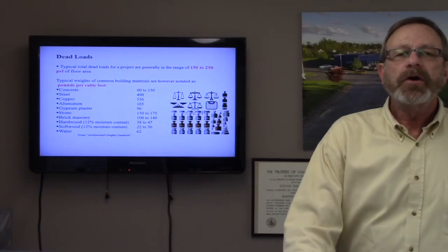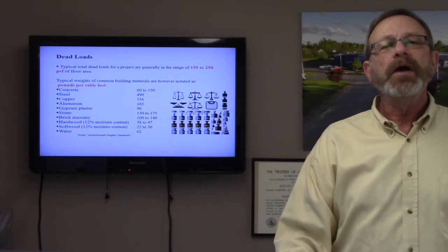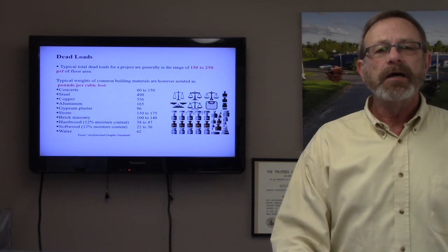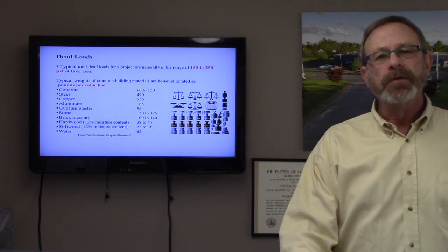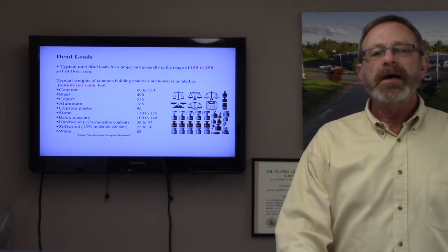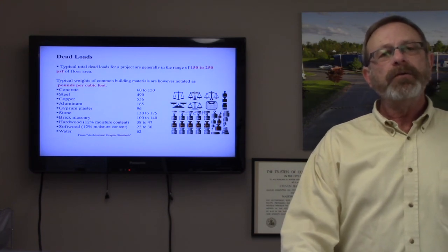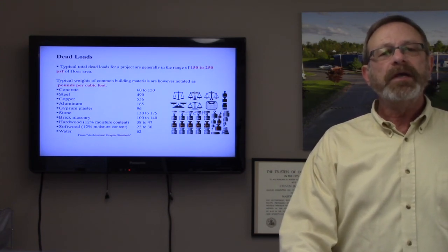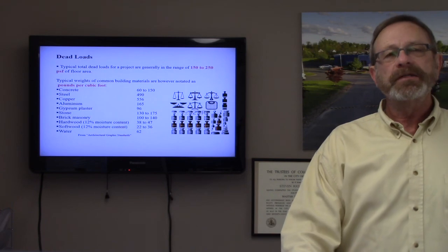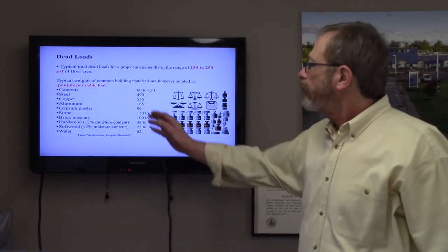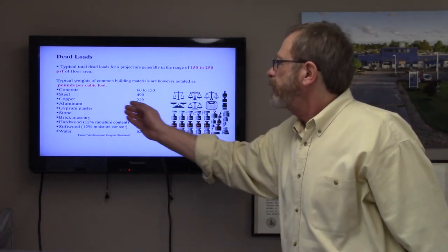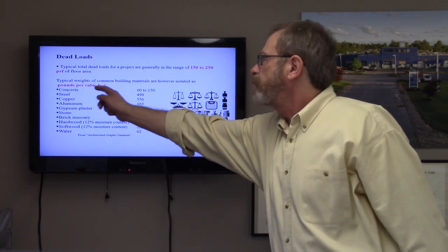You can see from this chart why we say that dead load weights are knowable, quantifiable, and therefore predictable. For the most part, it is the amount of dead load weight that varies from project to project. These dead loads are referred to as static loads. So here we have a computation of steel weight in pounds per cubic foot.